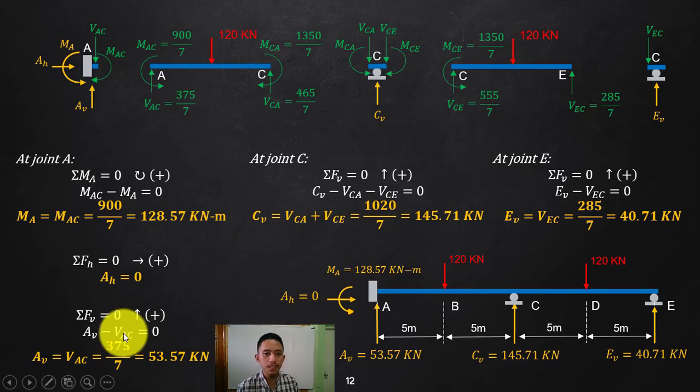So that's it. That is how we will solve. Once you have your support reactions, you can draw your loads, and of course you can draw your shear and moment diagram, making use of that. It depends on you what method of deformation you want to use. You can solve any deflection or rotation at any point, since you already completed the forces.